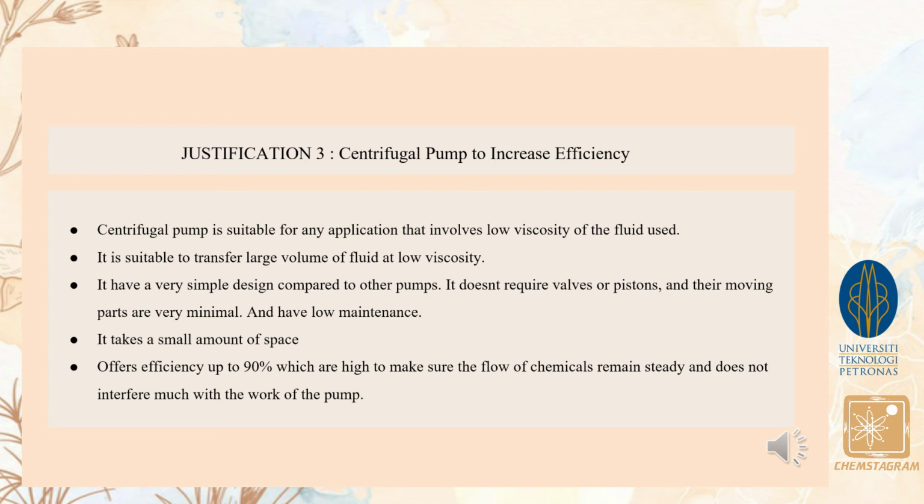The centrifugal pump is suitable for any application that involves low viscosity of the fluid used. It is suitable to transfer large volume of fluid at low viscosity. It has a very simple design compared to other pumps. It doesn't require valves or pistons, and its moving parts are very minimal and have low maintenance. It takes a small amount of space. It offers efficiency up to 90%, which is high to make sure the flow of chemicals remains steady and does not interfere much with the work of the pump.